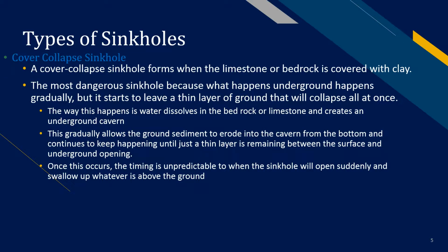Cover collapse sinkholes are the most dangerous of all of them. These are very highly unpredictable and happen very fast. The water dissolves the bedrock limestone and creates an underground cavern. This gradually allows the ground sediment to erode, and the cavern from the bottom continues to erode, with just a thin layer remaining between the surface and the underground opening. Once this occurs, timing is unpredictable, and the sinkhole could go at any time. These are more common in areas like Florida, and it's what happened in Kentucky with the Corvette Museum.